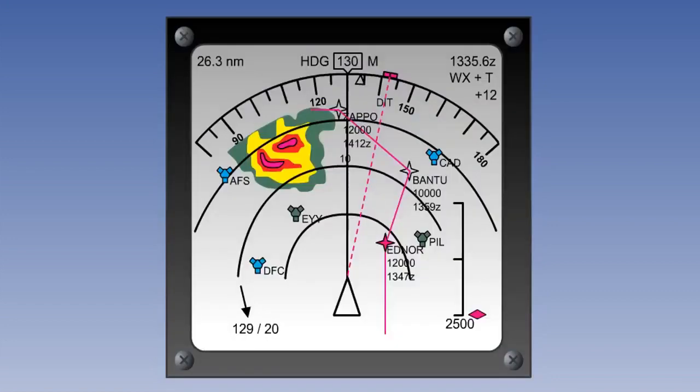Second, the APV, the approach procedure with vertical guidance. Here, glide slope information is produced by the internal navigation system, but is not generated from outside the aircraft, as is the case with the Cat 1 systems. It does have, however, vertical guidance, and so is more akin to the precision Cat 1 approach than a non-precision one. It therefore carries minima slightly higher than those of a Cat 1 approach, that is, decision height 250 feet and RVR 600 metres.